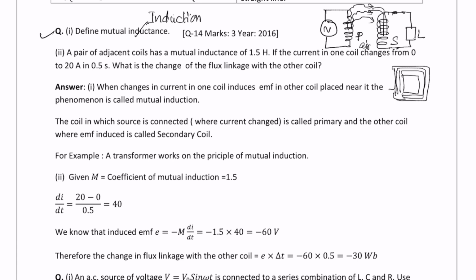So iron can carry more lines and gives an easy path. But there is an overhead in keeping iron. Anyway, we can communicate the primary flux to the secondary by keeping a ferromagnetic material or air, depending on how much the voltage is.